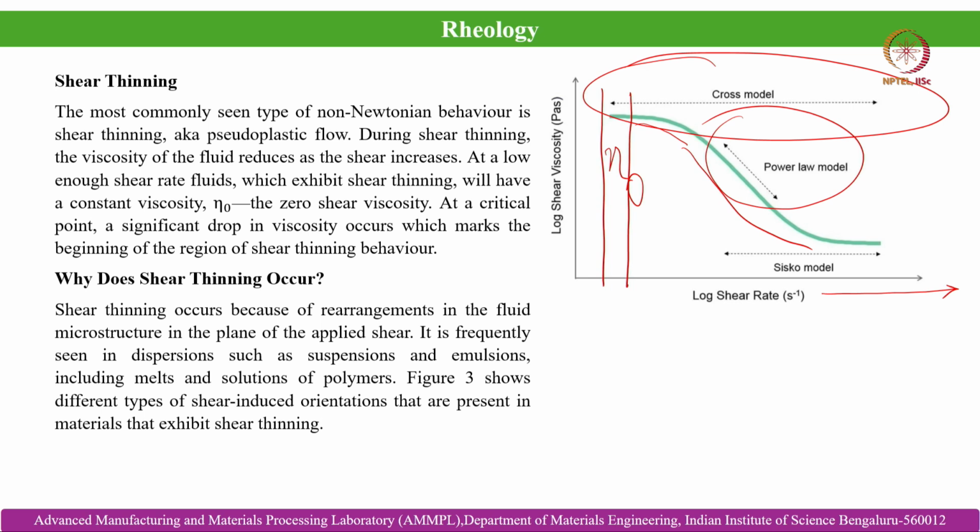So, why does the shear thinning behavior occur? You see, it is nothing but the rearrangement of the fluid molecules that causes the shear thinning behavior. And in case of a solidifying liquid melt, for example, say an aluminum copper alloy, the moment its temperature locally goes below the liquidus temperature TL, that is when T is less than TL.